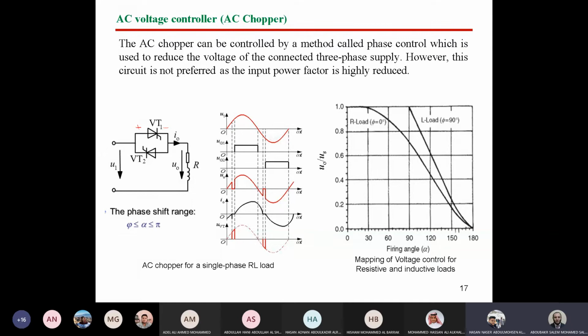The opposite, doctor, when applying a minus. No, it's not only opposite. It's not a condition to turn off the diode to be in opposite, or to turn off the supply. No, it's not like that. And turning off the supply is not a solution. When the current falls to zero, this is the condition.